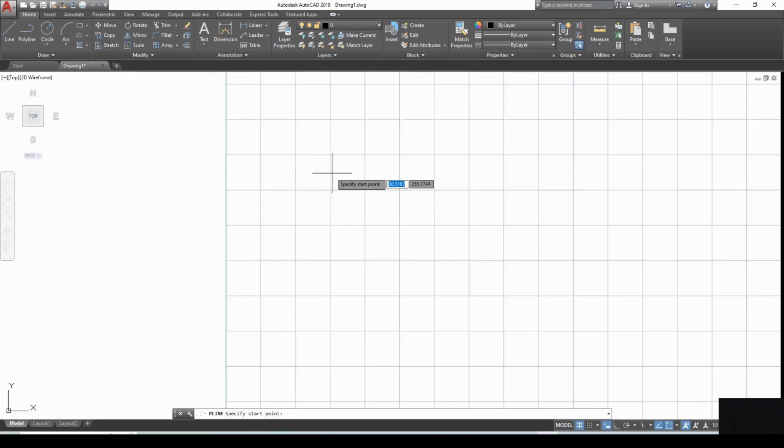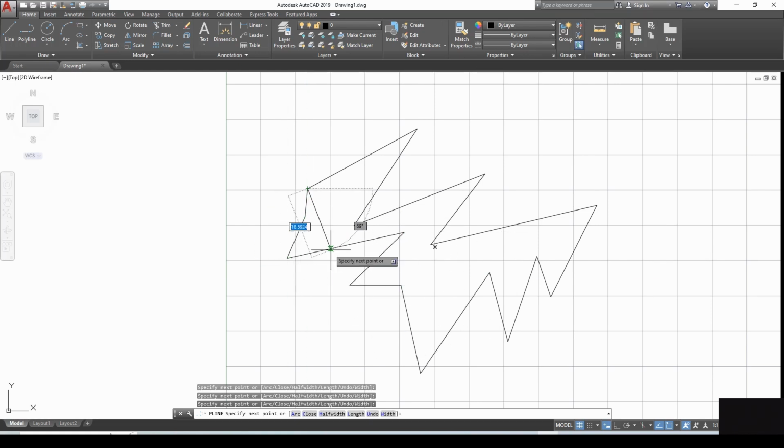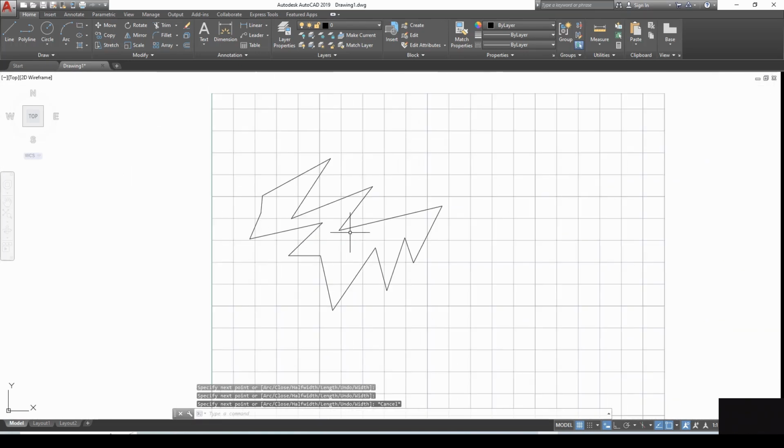So let's say this is the type of toolpath that you want to design. Using the tools of AutoCAD, you have generated this toolpath. You want to create a sequence of XY points and feed it to the CNC machine to test it out before you can write any generic algorithm for it. So you can do that.